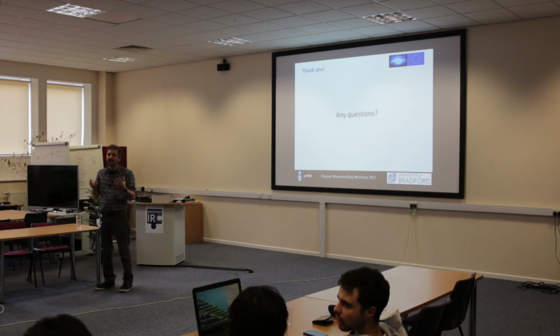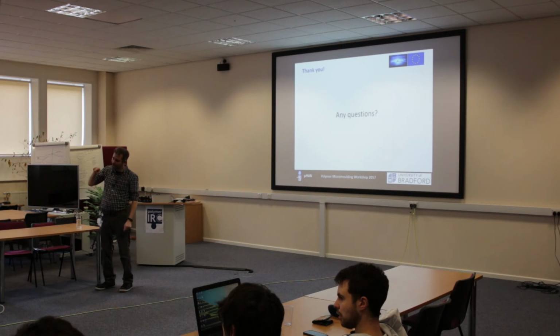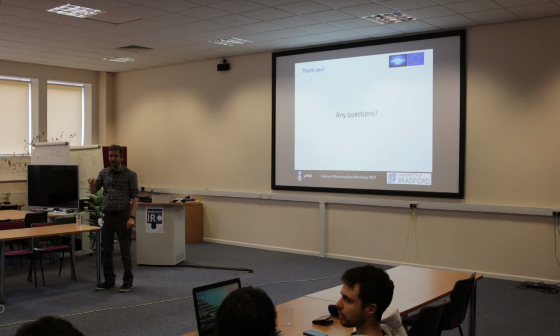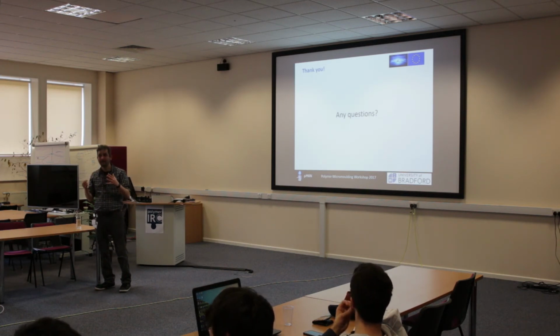One of the key things is they start to bridge. So if you look at the individual pellets, you're trying to force these pellets into a small hole. What happens if you've got moisture is they get a little bit sticky and they start to stick together until you end up doing what's called bridging. You end up bridging your material over the top, so nothing's going onto the screw. It's just sat there. And it's a real pain. It's really difficult to get around once that has started occurring. You need to strip everything, you need to clean everything out, and it's this horrible mass. So it's something you want to be careful about.